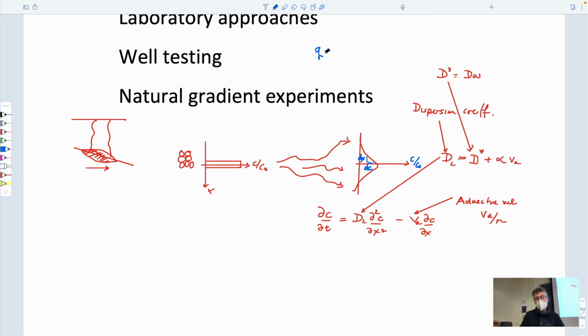Fick's law says that the mass flux is equal to the diffusion coefficient times the gradient of concentration with a negative sign on it. And so this is for chemical diffusion, and it's really just this part. But when we look at motion in groundwater, if it's in granular material, then the fact that this kind of spreading, this would be an individual trajectory of a particle of solute as it goes downstream, it tends to spread. And as it spreads, this peak has to be reduced from this, and this width has to be increased from this. It's a typical diffusion process.